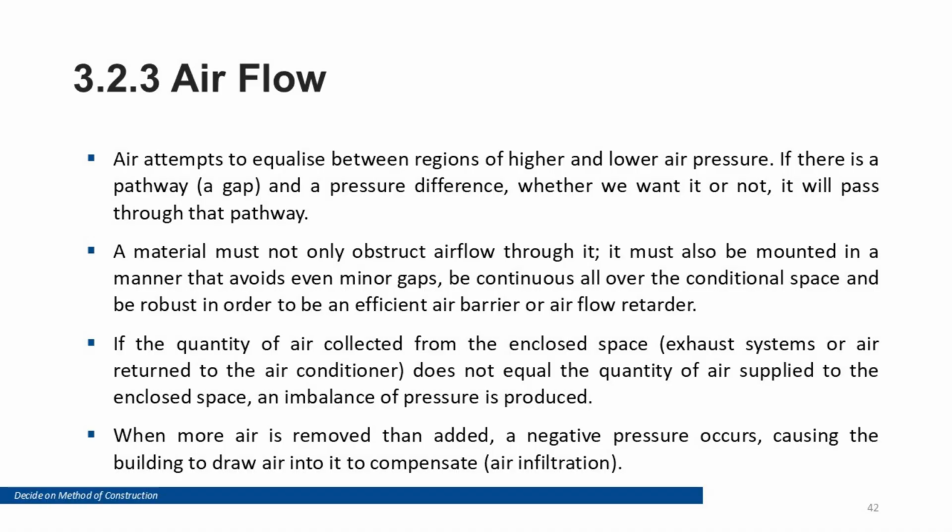Airflow. Pressure differences from wind, stack effect, and fans drive infiltration and exfiltration. If supply and exhaust are unbalanced, unwanted air movement increases. Airtight construction limits uncontrolled pathways, so ventilation can be provided deliberately and consistently, improving both energy efficiency and indoor air quality.